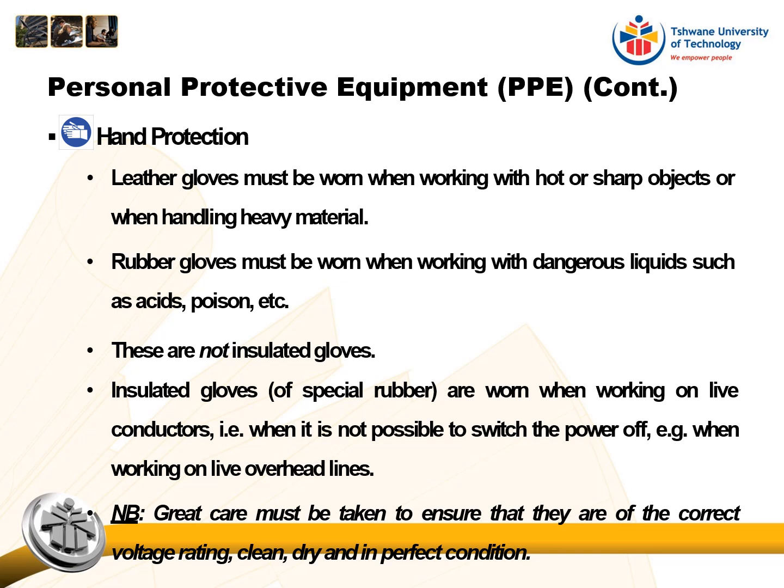Great care must be taken to ensure that they are of the correct voltage rating, clean and dry and in perfect condition. So you can wear these insulated gloves, but if you are working on a higher voltage level, then it will not be able to protect you. So you always check what is the maximum voltage level for these gloves that I'm using.